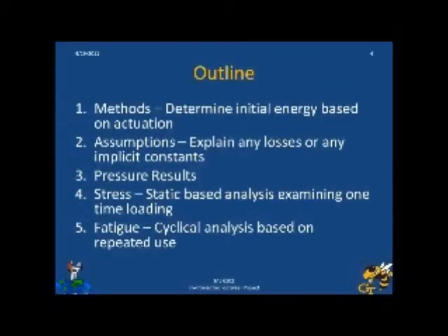These pressures will allow a static analysis on the structure based on respective material ultimate tensile strengths, after which a cyclical analysis will be performed on the component with the weakest static strength, ensuring a lifetime of safe operation. Finally, margins of safety can be generated on all these items that will provide substantiation to the bill of materials.